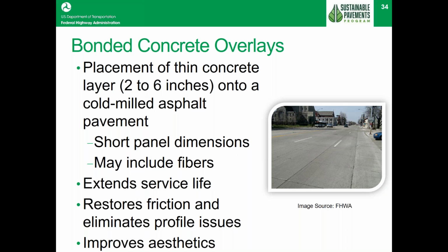Now, I've had some experience with this. We did one of these up in New Jersey. It was on an off ramp where the trucks had come around it, and it was difficult because the roadway kept shoving off there, and the state had to go back in and replace that pavement almost on a yearly basis. And after we put this bonded concrete overlay on that, we had gone back after about 5 years, and most of it was still in pretty good shape.